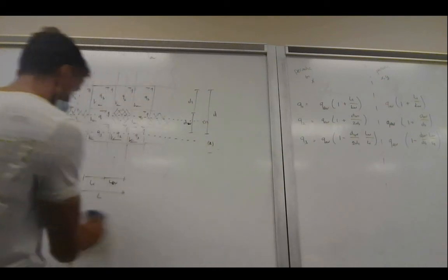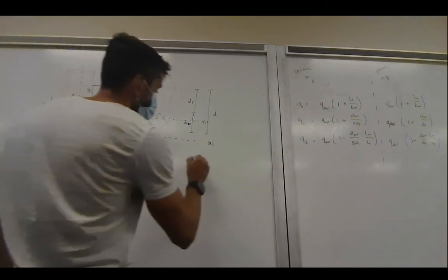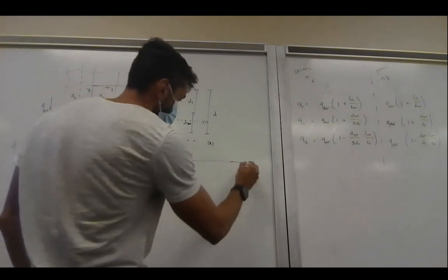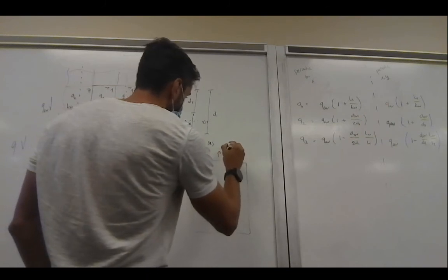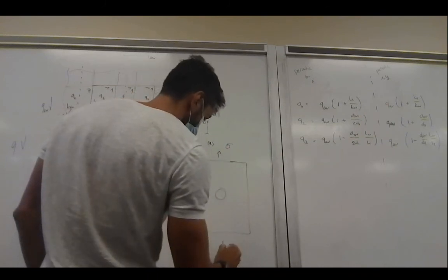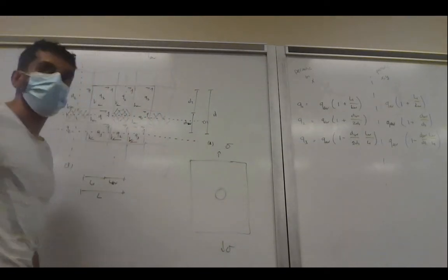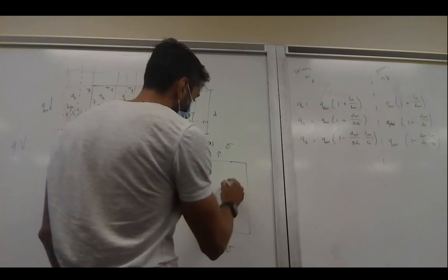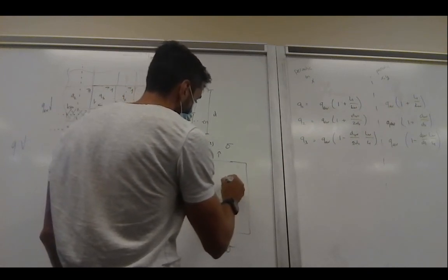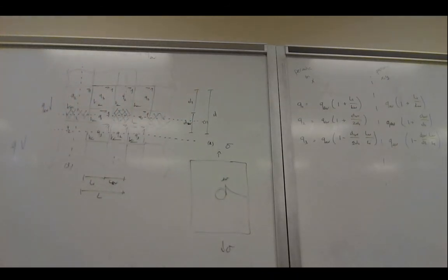Let's do this most simple case. A plate with a hole. So you load this with a certain sigma. So this is our applied sigma stresses. But if you then look at a cutout, here you will have a stress concentration that is basically 3 at this edge. So the peak stress is 3 times as high as your far field load.